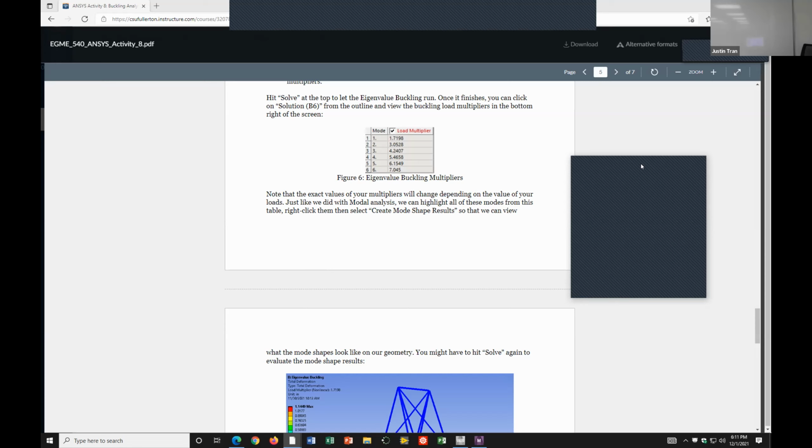Yeah, so go back to it, and I just want you to keep on the value, and right now it's maximum. So the maximum deformation is 0.2. And I want you to change the axial mode. So let's go ahead and change it to minus 9. Okay, and then go ahead and run it.